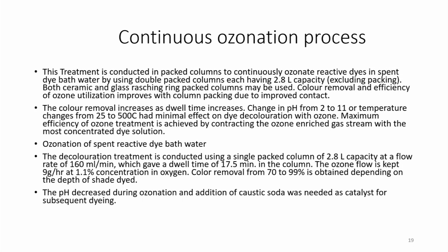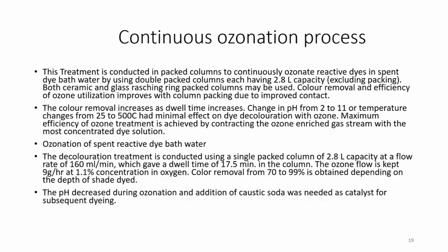The color removal increases as dwell time increases. Change in pH from 2 to 11 or temperature changes from 25 degrees to 50 degrees had minimal effect on dye decolorization with ozone. So, that means it is not temperature dependent, but definitely it is pH dependent. Maximum efficiency of ozone treatment is achieved by contacting the ozone enriched gas stream with the most concentrated dye solution.